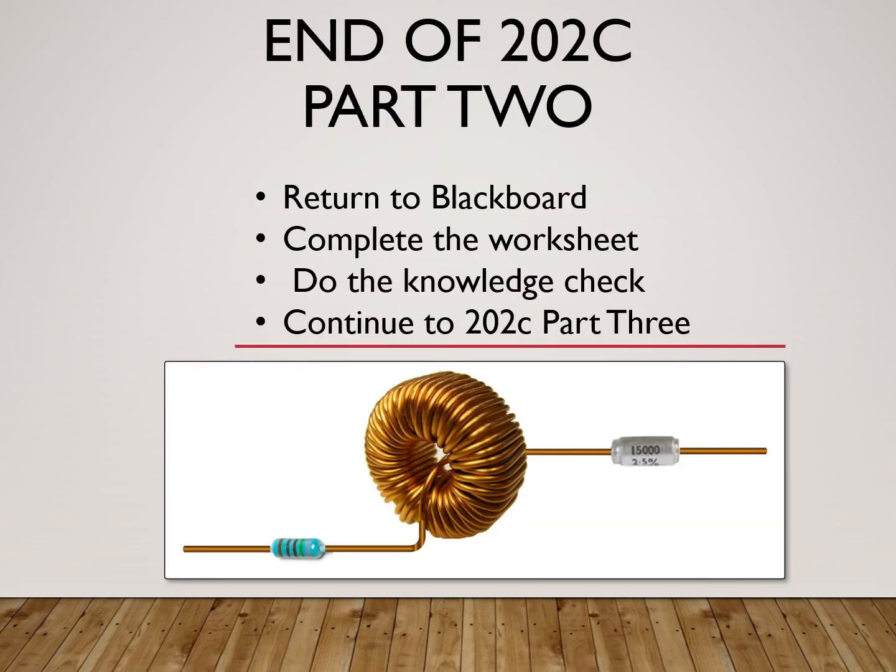This brings us to the end of part 2 of 202C. What I want you to understand from this part is how changing the resistance affects the total impedance, and how changing the capacitive reactance and the inductive reactance will also change the total impedance, and what that does to the circuit as a total. How does that affect our power factor? Why does building an XC value offset my XL value? What is happening with our power dynamics as far as my Q, my S, and my P are concerned as well? Go ahead and return to Blackboard, do the worksheet, as well as the knowledge check, and then you can continue on to 202C Part 3.